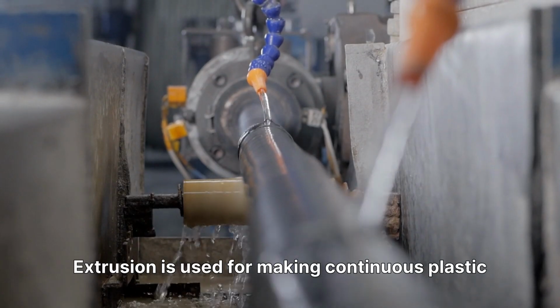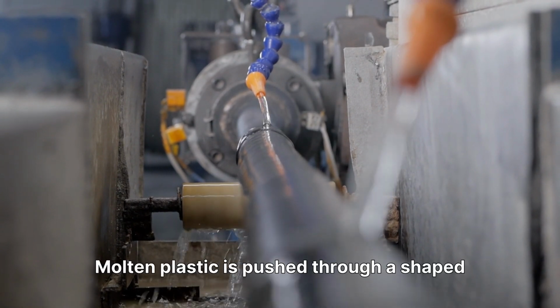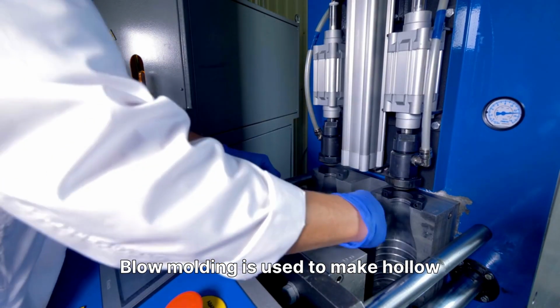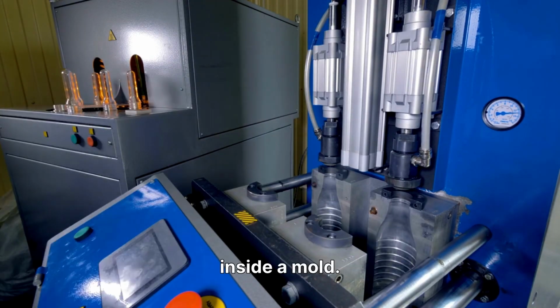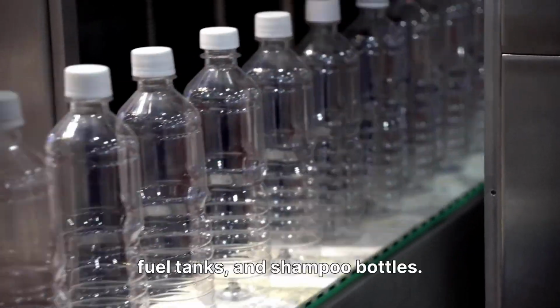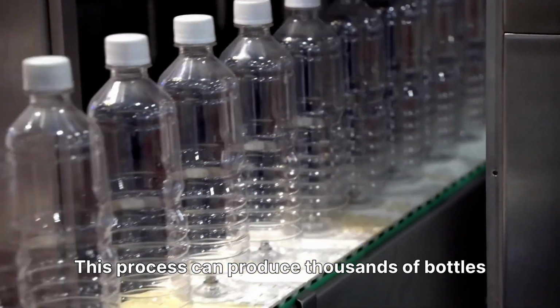Extrusion is used for making continuous plastic shapes. Molten plastic is pushed through a shaped die. This creates products like plastic pipes and window frames. Blow molding is used to make hollow plastic objects. A tube of hot plastic is placed inside a mold. Compressed air inflates the plastic like a balloon. The result is products like water bottles, fuel tanks, and shampoo bottles. This process can produce thousands of bottles per hour.